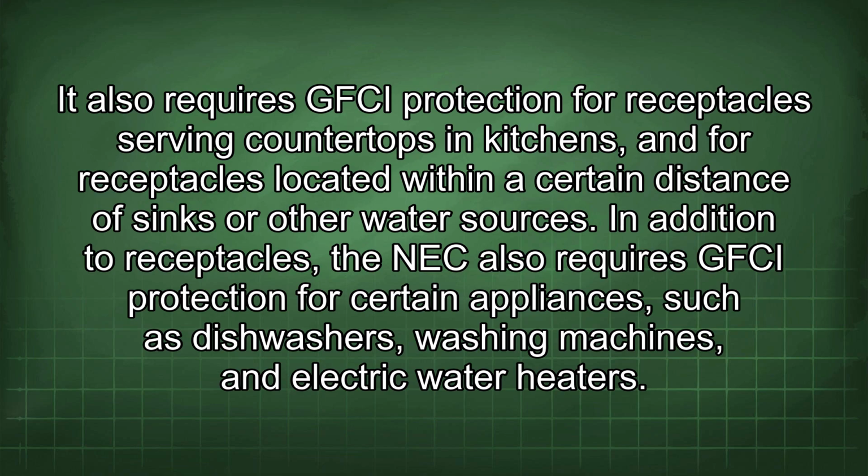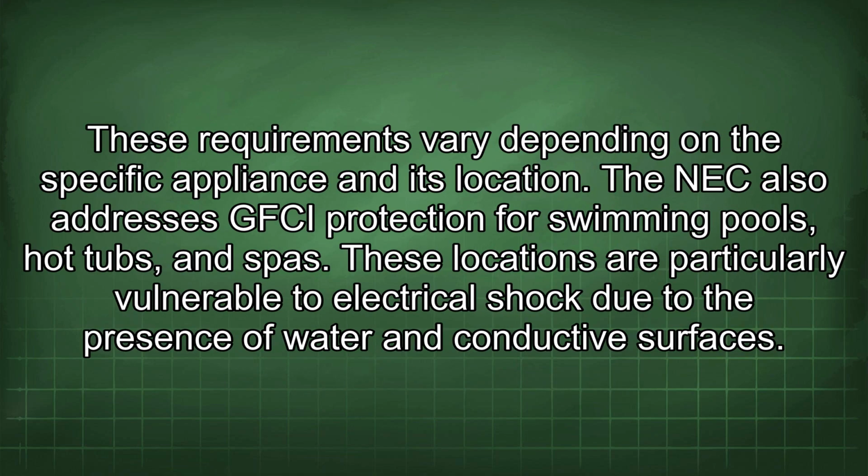In addition to receptacles, the NEC also requires GFCI protection for certain appliances such as dishwashers, washing machines, and electric water heaters. These requirements vary depending on the specific appliance and its location. The NEC also addresses GFCI protection for swimming pools, hot tubs, and spas.